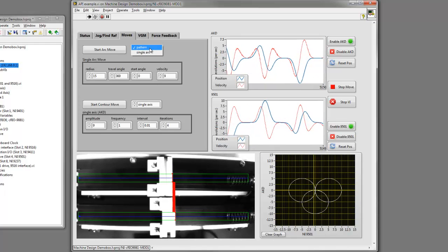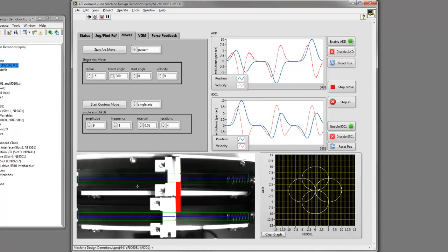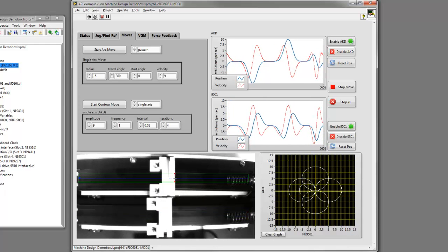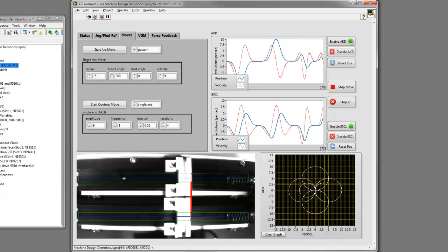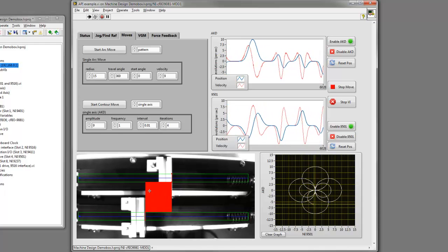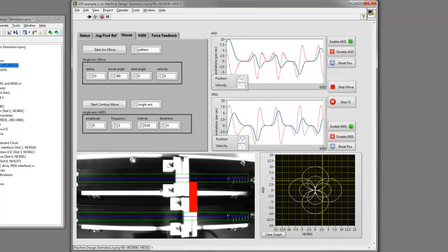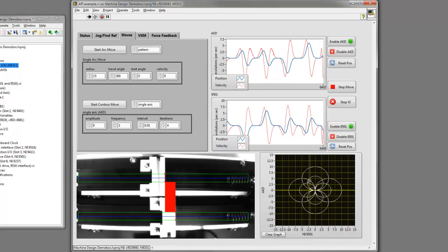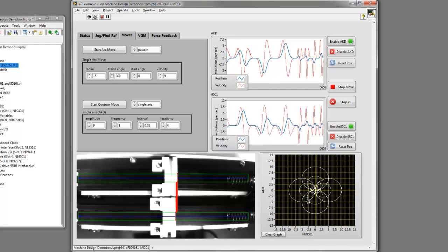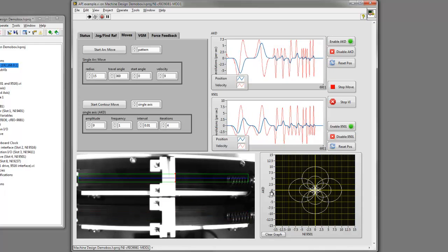And this is the pattern example. And you can see my vision code is always running in the background, so I'm always computing the distance between these two front edges and these ROIs. I'm not actually using that information right now, but I am graphing and plotting it. I'll use this information when I go into my vision guided motion case. So you can see I'm doing consecutively smaller arc moves to do circles. Okay, and my move stopped.